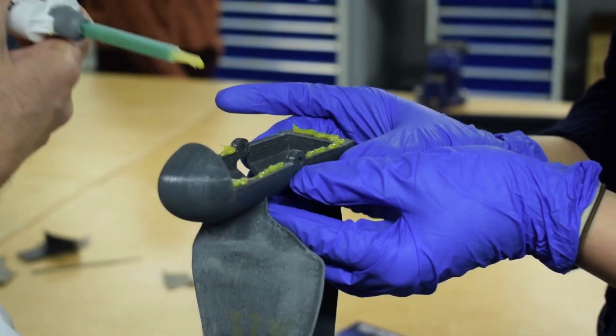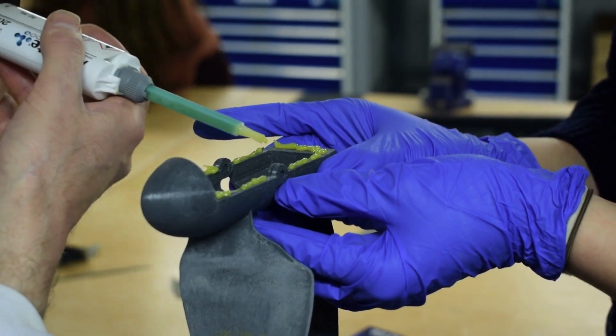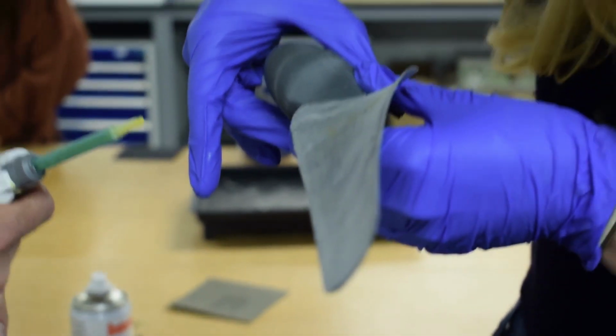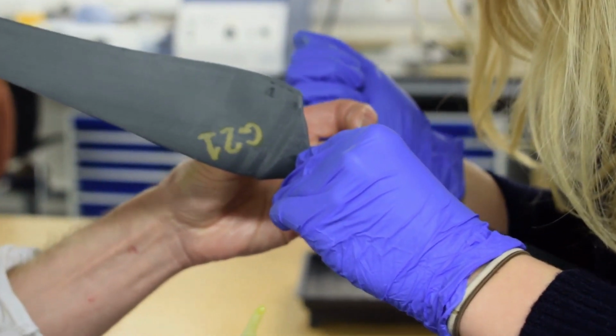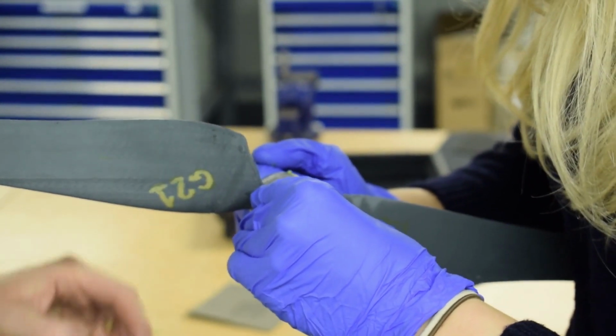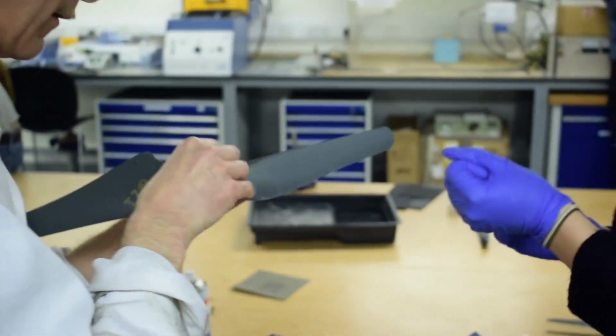The two mating faces of the turbine were also sanded, cleaned, and then glued together into the final turbine assembly. The additional surface area offered by the interlocking teeth on the edge, as well as the orthogonal surface of the nose cone, ensured maximum glue surface contact so that the assembly wouldn't fly open during testing. After waiting a week for the glue to cure, a final sanding of the nose cone was completed to make sure it too was as smooth as the blades, and to remove any dried glue residue from the surface.